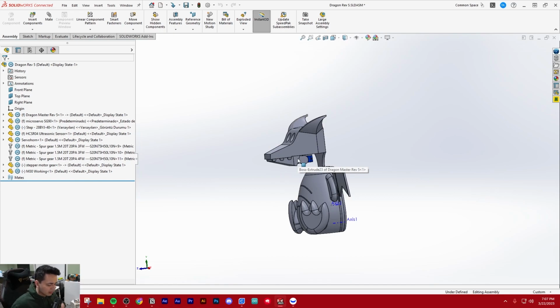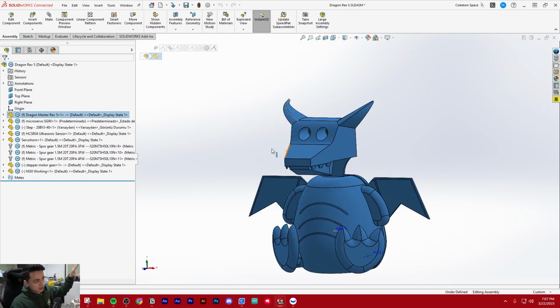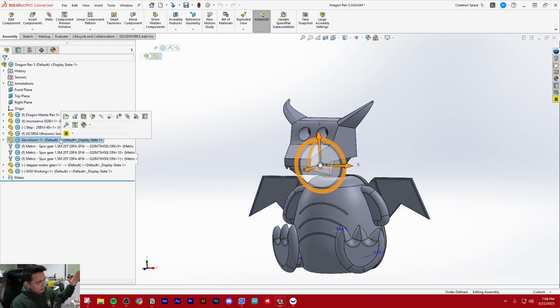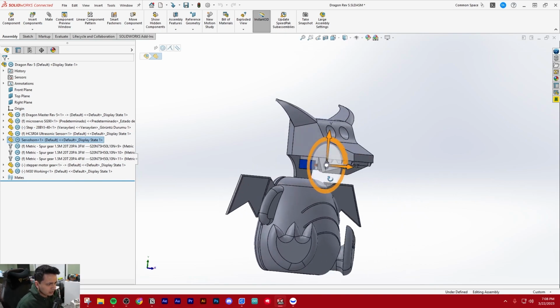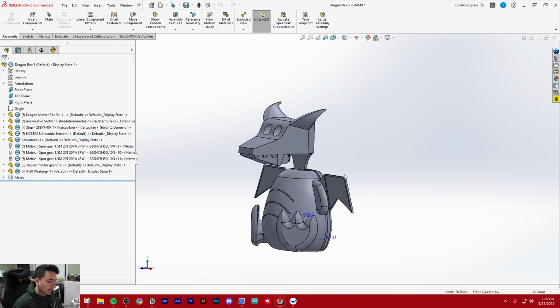So all of my parts that I'm actually designing that will be printed, that goes in the part file that's a master. And then I bring that part file into my assembly, which is this top thing. And then all of these other things are components or other pieces of hardware that are interacting with my plastic parts. So that's a really good way to model to keep everything clean and organized. I'm going to walk you through exactly that, but it's important to understand from a higher level how we're going to get there.